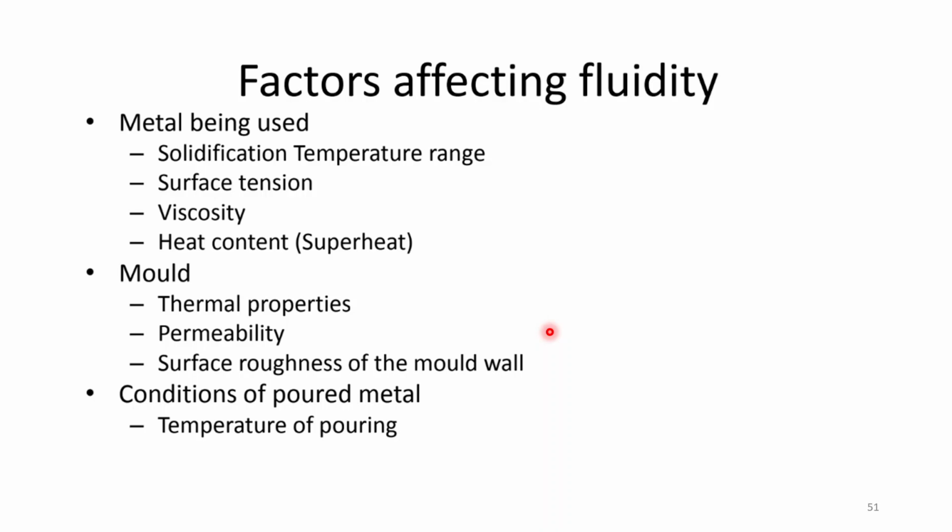Okay, next are the factors that affect the fluidity. So why is fluidity required? Fluidity is required in case you want to make some intricate shapes, or get good filling of your mold cavity to reach each and every part of the final complex shape. So if your material has good fluidity, then you can form complex shapes very easily.